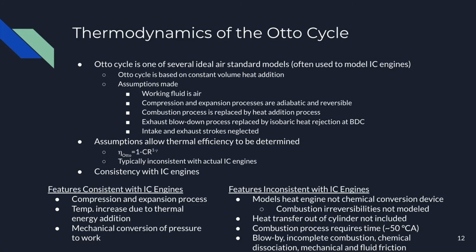As I had mentioned before, there's heat transfer out of the cylinder, which the Otto cycle doesn't necessarily account for. The combustion process in the Otto cycle occurs at top dead center, whereas in an actual IC engine, you'd see that across a wider range of crank angle degrees. And then some other things: blow-by, incomplete combustion, chemical dissociation, and mechanical and fluid frictions aren't accounted for either.